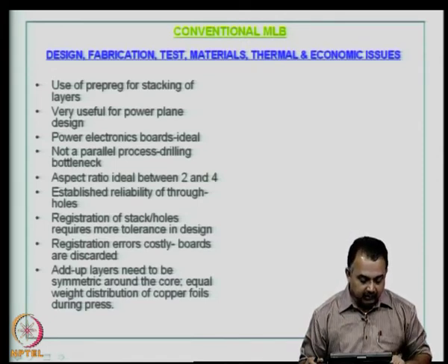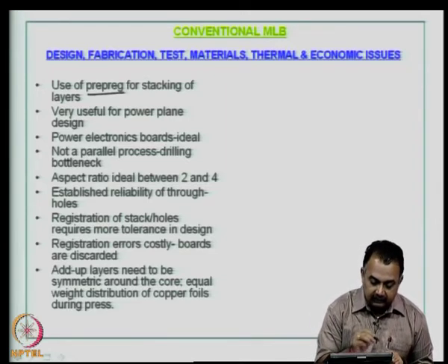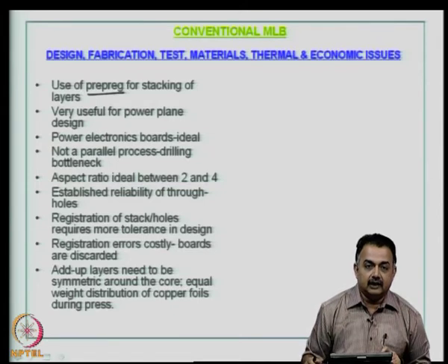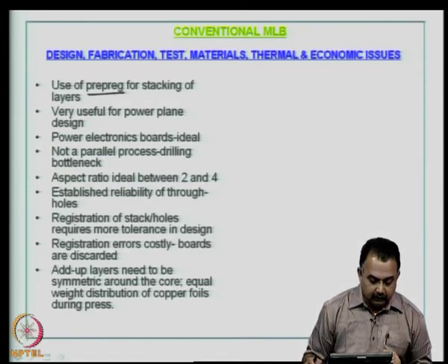In the conventional multilayer board technology, you have to use a prepreg material for stacking the number of layers that you require in the design. This is very useful for power plane design.